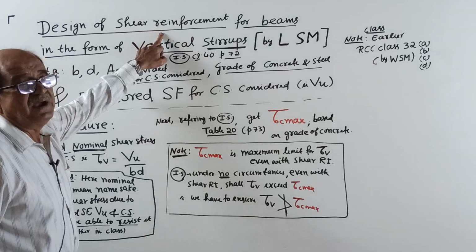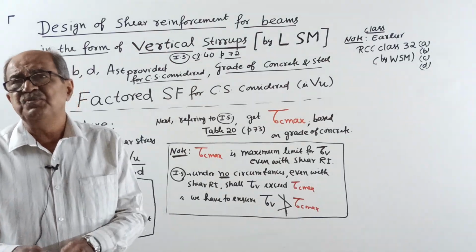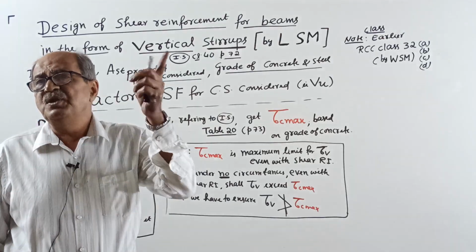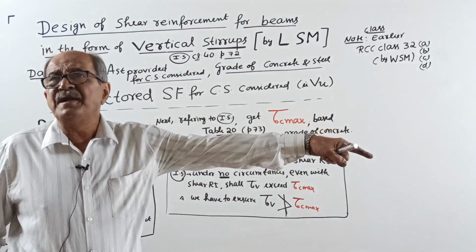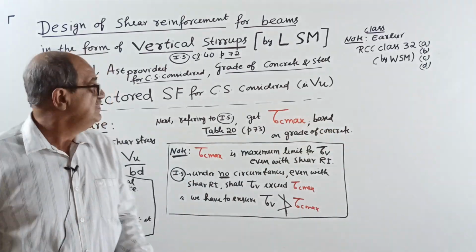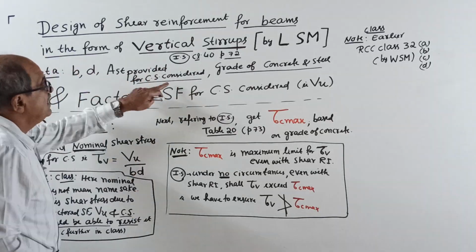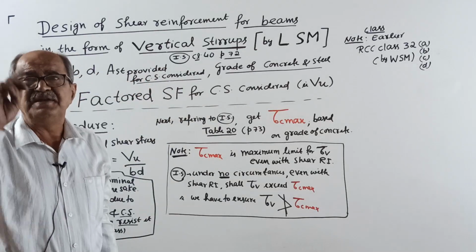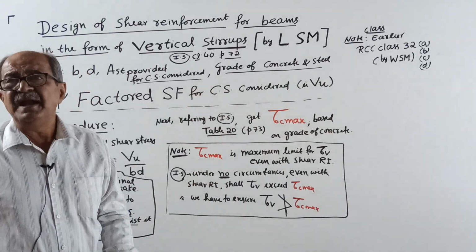Design of shear reinforcement is usually done for maximum shear force. Maximum shear force will be at the support. So when you consider the cross section at the support, the mid-span provided 4 bars will not be there. Only 2 bars will be there. That you require: AST provided for the cross-section considered. More and more I told in working stress method. Remember, here I am giving data.